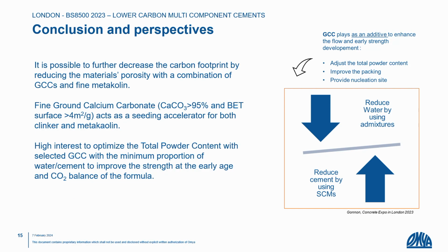Finally, you remember the figures with the development of strength versus the water to cement ratio. Even if it seems to be simple, with this figure, we can try to find which combination can be used to reach 20 MPa or 8 MPa. So this set of model formulations is just a proposition to be able to consider the mineral addition in a new way and to prepare the combination that will be done by the engineer in the concrete lab and after on site.